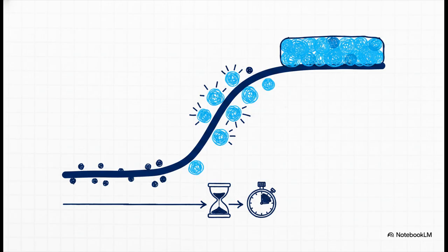Finally, we cannot talk about phase transformations without shifting our focus from temperature to the absolutely crucial dimension of time. We actually track how these transformations progress kinetically using the Avrami equation. This elegant little formula plots the fraction of transformed material against time, which gives us classical S-shaped kinetic curves. It's a perfect visualization for how transformations start off slow during nucleation, absolutely take off and accelerate rapidly during growth, and then gradually taper off as all the growing phases start crashing into one another.